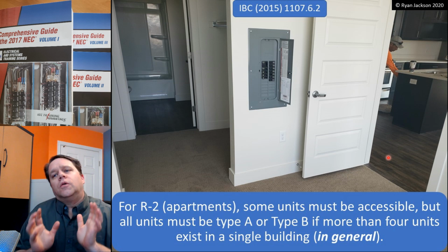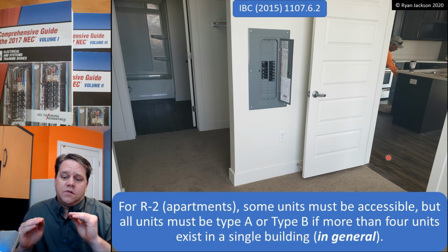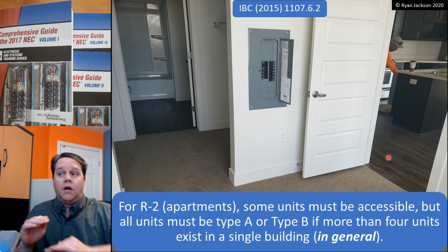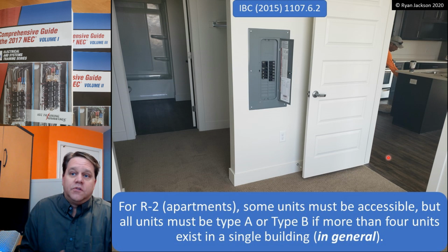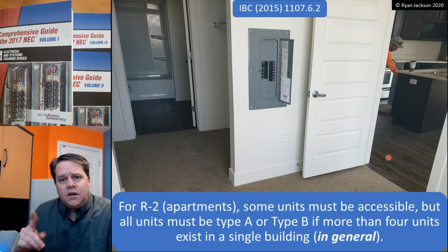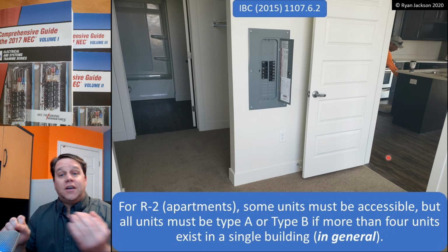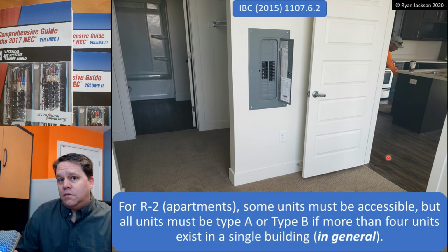We have full-blown accessible. If I'm in an accessible apartment, that means that my toilet room has 5 feet, it has grab bars, I've got a roll-in shower or a transfer shower, full-blown 100% accessible. Type A and Type B you could almost look at and call adaptable. In other words, I don't have to have the grab bars in the toilet rooms, but I do have to have backing in the walls so that I could mount grab bars if I ever needed them.